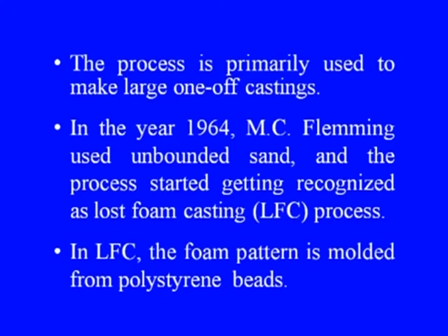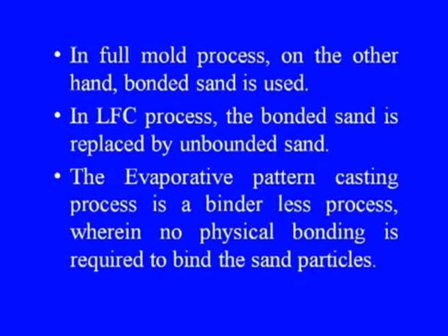In the year 1964, M.C. Fleming used unbonded sand and the process started getting recognized as the lost foam casting process, also known as the LFC process. In the LFC, the foam pattern is molded from polystyrene beads. In the full mold process, on the other hand, bonded sand is used. In the LFC process, the bonded sand is replaced by unbonded sand. The evaporative pattern casting process is a binderless process, wherein no physical bonding is required to bind the sand particles.